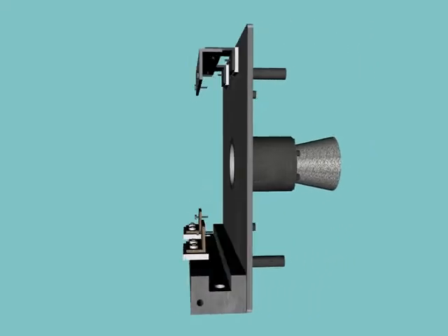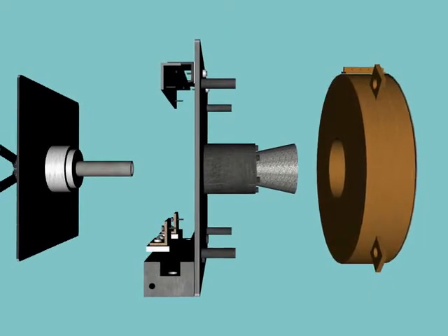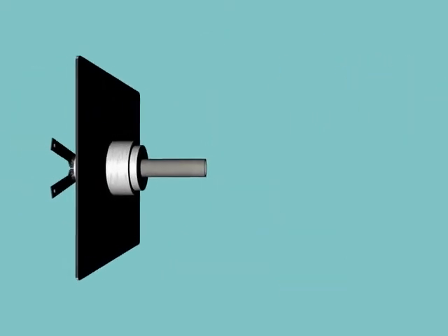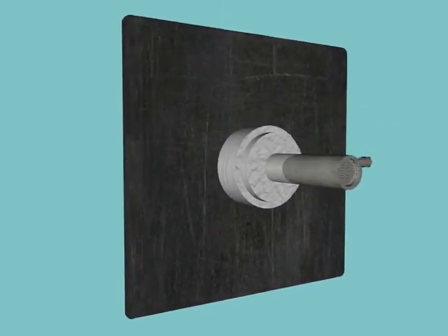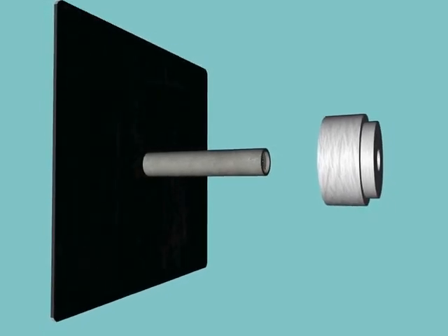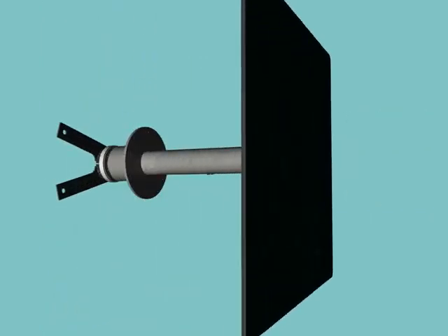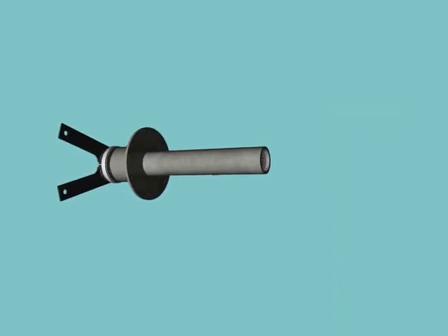We'll now move on to the next part of the system, the cathode assembly. In order to electrically insulate the cathode from the anode plate, we use the boron nitride insulator shown here. Behind it, the cathode plate structurally holds the cathode assembly and is at cathode potential.